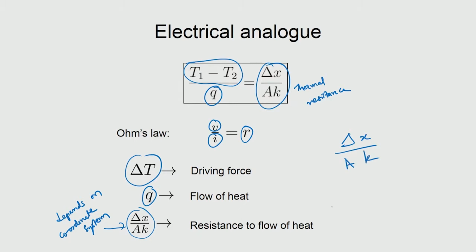What it implies is that if the thermal conductivity is increased, that means it is able to send the heat across very easily. Therefore, the resistance should come down. If there is a cross sectional area that is large, that means the heat can go across a larger area. Therefore, the resistance is less, and if it has to go over a longer distance, then that also means that the resistance is more. So, the proportionalities are as we can already imagine from our daily life experience, but we now have a mathematically defined way to look at what is called the thermal resistance.